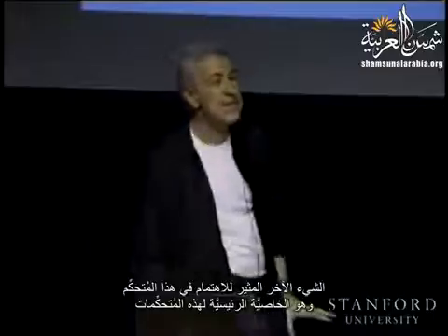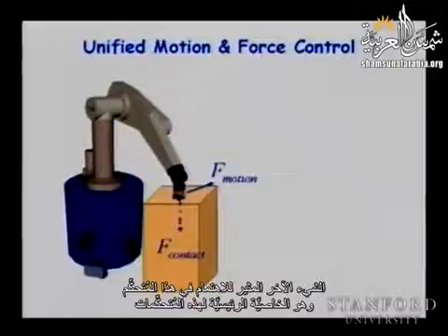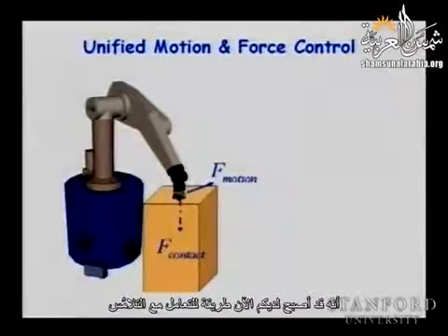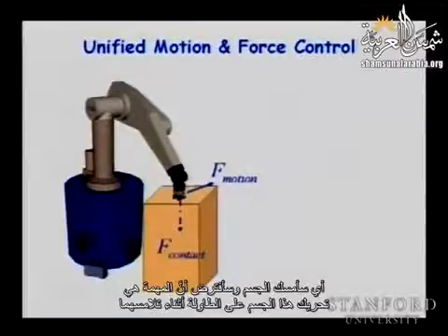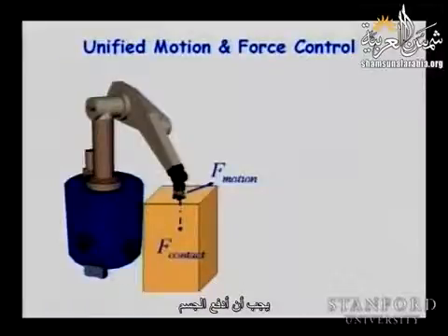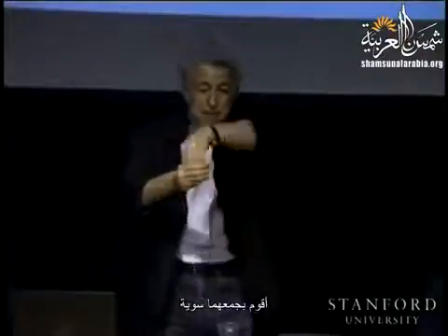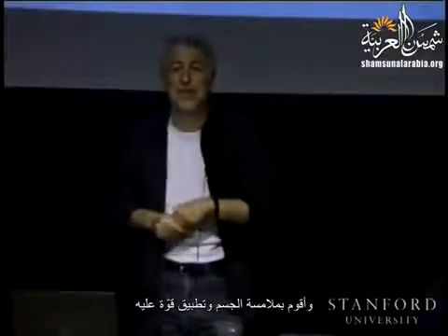The other interesting thing about this controller, and this is really the fundamental property of those controllers, is the fact that now you have a way to deal with contact. Because when we are going to move this object, I grasp the object, and suppose the task is to move this object over the table while it's in contact. And I need to push on the object. I'm doing some assembly, and I'm touching the object and applying a force.